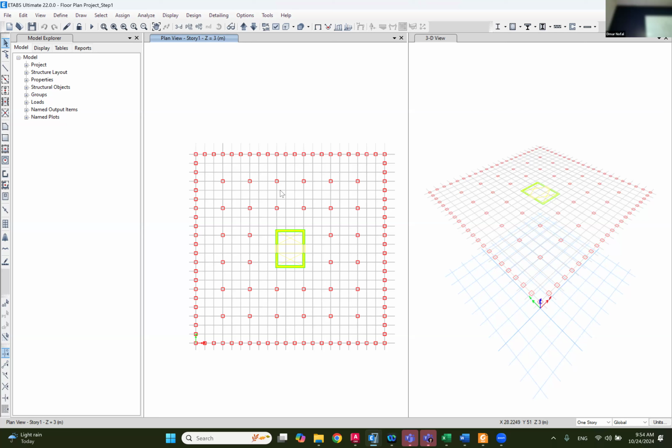All right. So one thing that I want to tell you guys, when you build this model, try to use high performance concrete material. If you use the 4000 PSI, or the materials that are in ETABS, that's the one that is used in regular buildings. And it's okay, we use it also in tall buildings, but we don't use it for the columns and shear walls. Columns and shear walls need to be in ultra high performance concrete, like mega strengths. Strength is very high. The compressive strengths sometimes reach 100 megapascal.